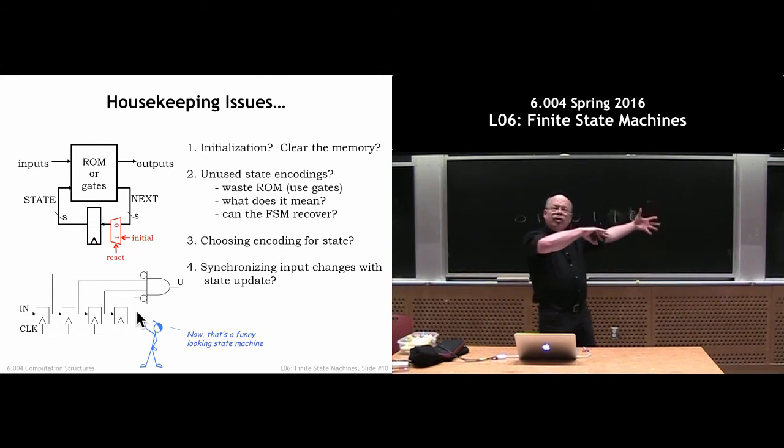Well, I've shown you the most general way with a state transition diagram. Here's a much simpler way of remembering the history and decoding it directly. So this logic is probably smaller and cheaper than the one I carefully drew. Part of the fun of engineering is, hey, wait, can I think of a clever way of doing this? And so this type of more or less direct encoding of the history using a shift register is actually often the simplest. It's one of the things that I always think about when designing state machines.